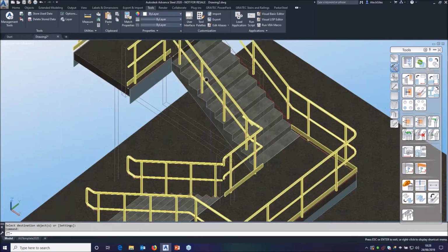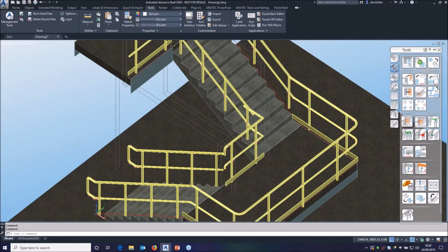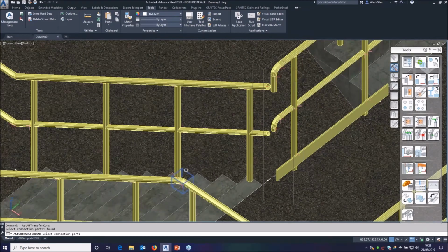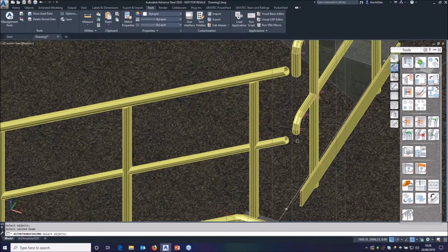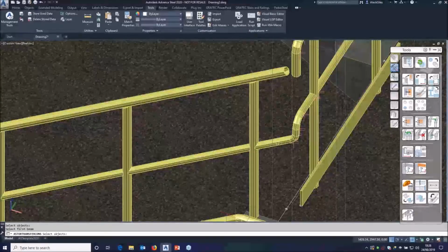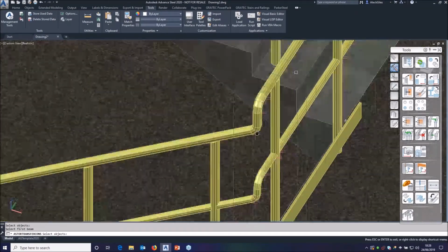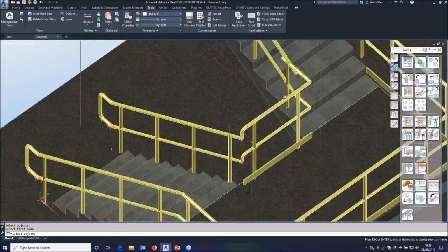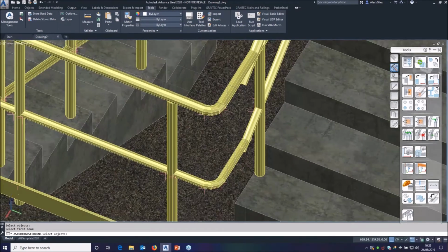Wonderful. Now we've already done pretty much all the hard work. There's not much left to do. I'm just going to get that railing joint again with that small radius and use that to touch up everything else. So literally I can go from that middle rail to that down stand, and that creates my swan neck. I can do the same for these pair. There you go. There's the swan neck finished. No nightmare of drawing polylines and trying to get 3D curves or anything like that. Just do these to the horizontal portions, and then likewise onto the slopes.